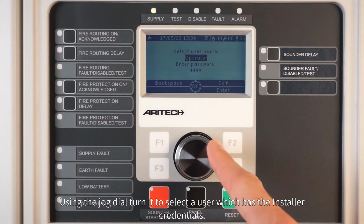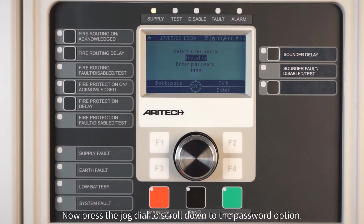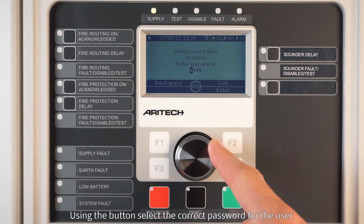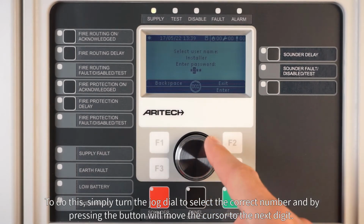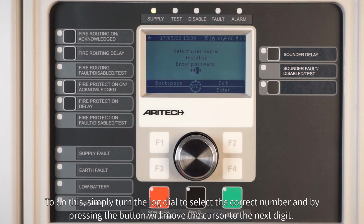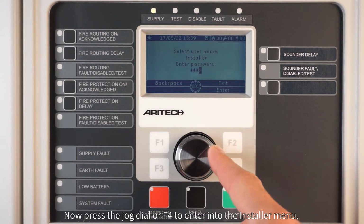Using the jog dial, turn it to select a user which has the installer credentials. Now press the jog dial to scroll down to the password option. Using the button, select the correct password for the user. To do this, simply turn the jog dial to select the correct number, and pressing the button will move the cursor to the next digit. Now press the jog dial or F4 to enter the installer menu.